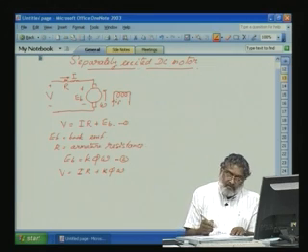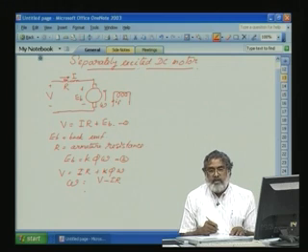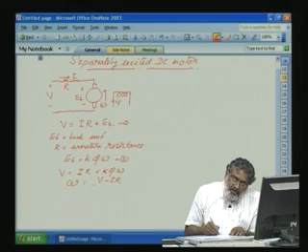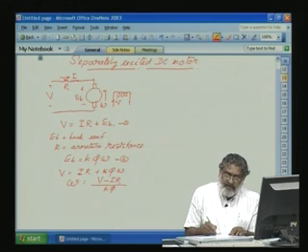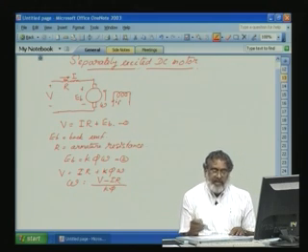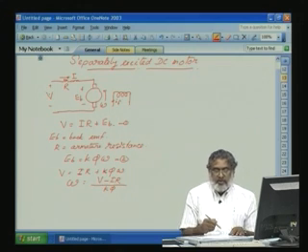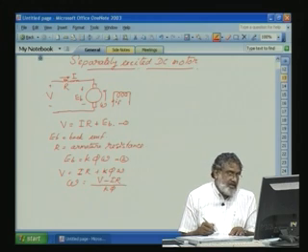From this, what is omega? Omega is equal to V minus IR, that is the armature drop, which depends on the resistance and the load current and sometimes can be neglected, divided by K phi. We are going to have the control of the machine through V. For speed control of omega, the only parameter we can control is V, that is the applied armature voltage.